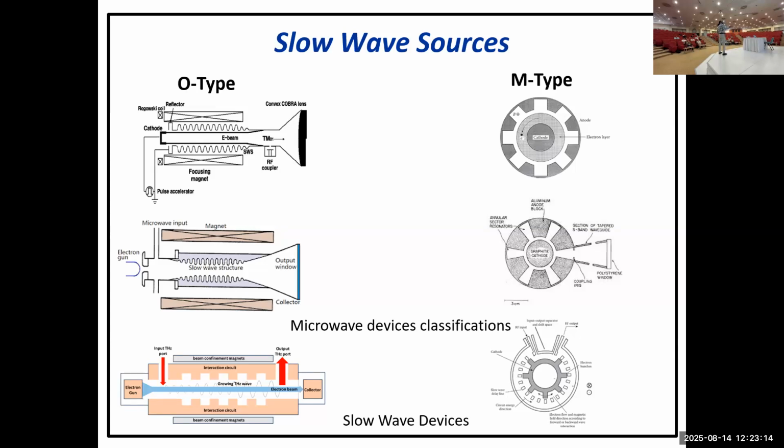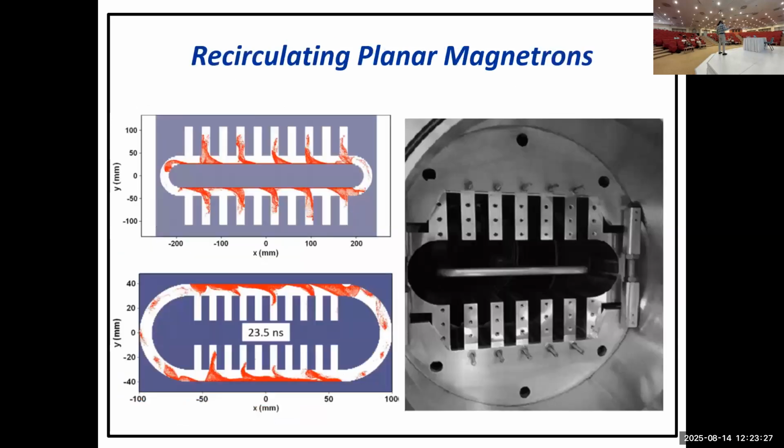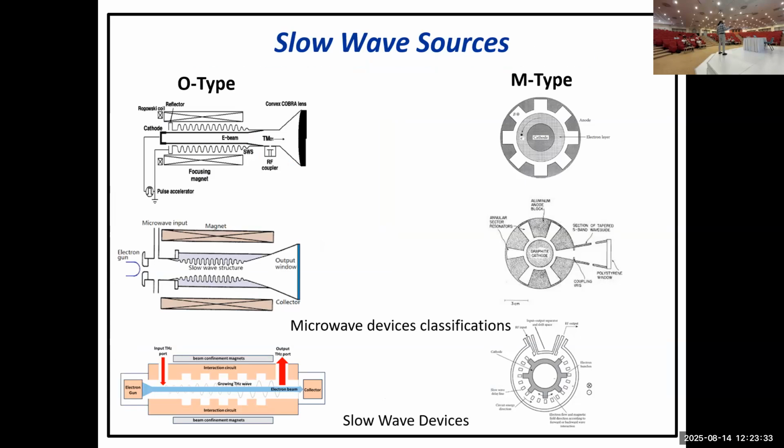So there is another crossed field device. This is called crossed field because they are perpendicularly crossed. This is the CFA, which is basically, if you take a look at the inverted magnetron, the cavities are inside here. So you can do the same idea: the cavities inside, and the cathode outside. And you can inject the RF to be amplified and then extract it. This is called CFA. It's not well studied.